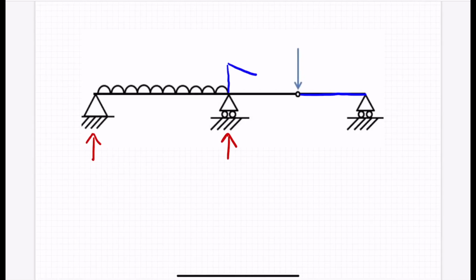Because that concentrated load is the only force we are dealing with, we have a linear variation as we go from right to left. Now, the moment we go just to the left hand side of this support, we're dealing with three forces like this UDL, which is really complicated. So from here I'm going to start from this side of the beam and go left to right.